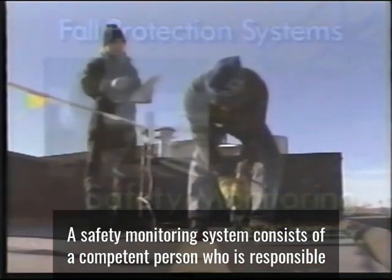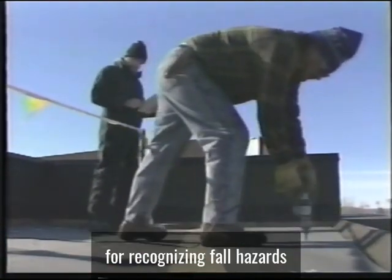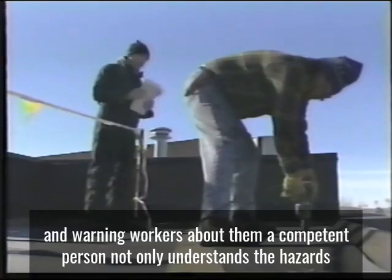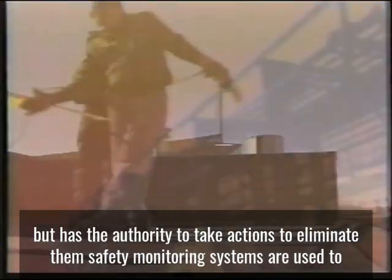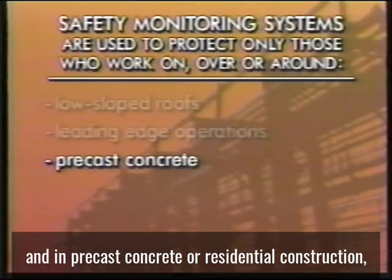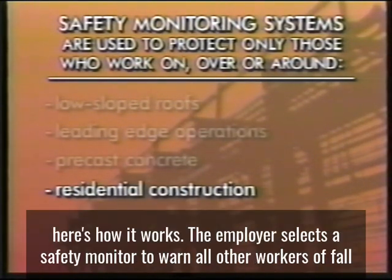A safety monitoring system consists of a competent person who is responsible for recognizing fall hazards and warning workers about them. A competent person not only understands the hazards, but has the authority to take actions to eliminate them. Safety monitoring systems are used to protect workers on low-sloped roofs, in leading-edge work operations, and in precast concrete or residential construction. Here's how it works.